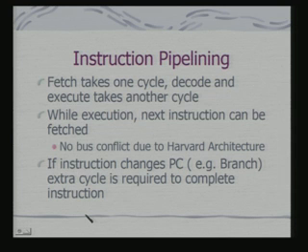So, obviously, I can have instruction pipelining. Okay, you can ask your question. For more efficiency, why did we only go for 4? We have gone for 4. This is an example of an architecture by 4. This was the demand of the internal design, because this processor, I said, is for low end applications. So, it is not required to support extensive multi-stage pipelining. When you go to a complex processor, you will find more complex multi-stage pipeline support. Here it is just a support such that I have an overlap of an instruction execution and instruction fetch.